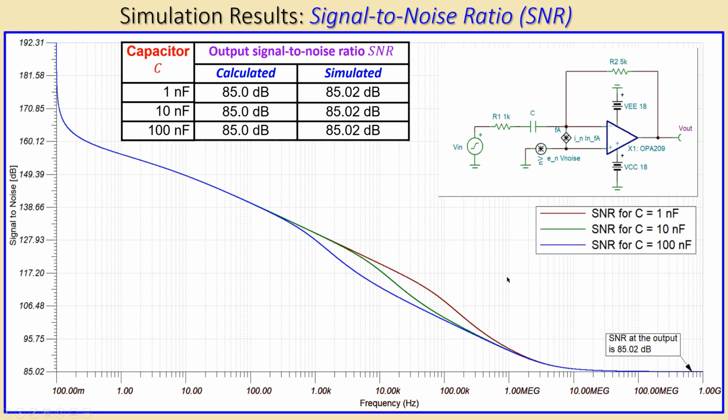So that was for this example number 6 about an inverting amplifier having a series RC high-pass filter. This is also called the differentiator, but of course it has a higher upper cutoff frequency. So in total, if you look at the plot again and the Bode plot, it is a bandpass filter.